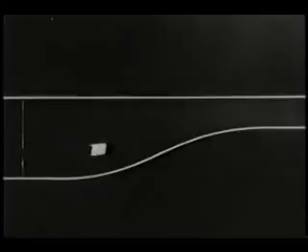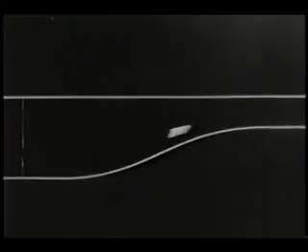The velocity field is shown here in half of a symmetrical contraction by tiny hydrogen bubbles electrolyzed at a wire in the water. Each fluid patch accelerates and shows the velocity increase with distance. Because of this velocity gradient, the front edge of each patch moves faster than the rear edge, and each patch stretches out. Water is nearly incompressible, and the flow is two-dimensional. So the area of each patch cannot change, and it becomes thinner, as well as longer.